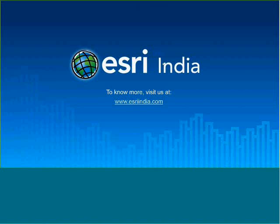Yes, it's a nice question. Yes, CityEngine has the capability to include topographic elevation. We can add a base map, also a digital elevation model. So the buildings which we are trying to create align themselves to the terrain. The moment they align themselves to terrain, it involves your terrain undulations and the topographic elevation. The process is that we add the digital elevation model or the topographic elevation available with us and align our 2D shapes to the elevation model. So this aligns them to terrain, and accordingly we can make use of topographic terrain in our 3D modeling.